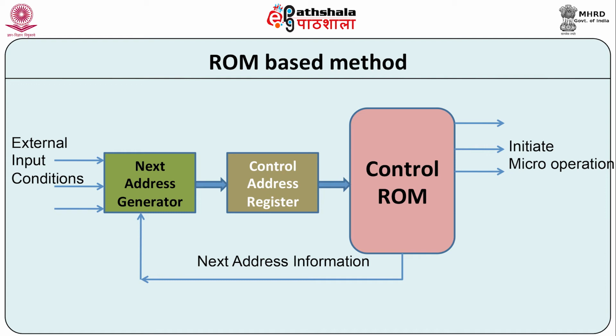Some of the bits of the present micro instruction are used to control the generation of the address for the next micro instruction. This indicates that the output of next address generator is a function of external input conditions as well as next address information obtained from control ROM.